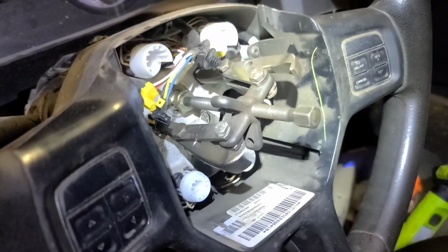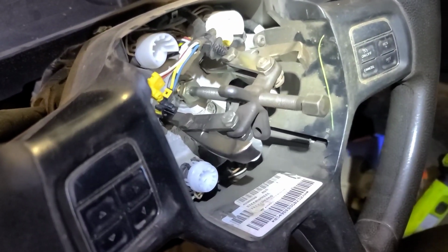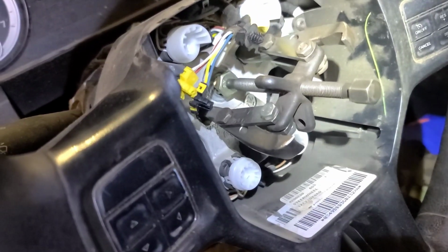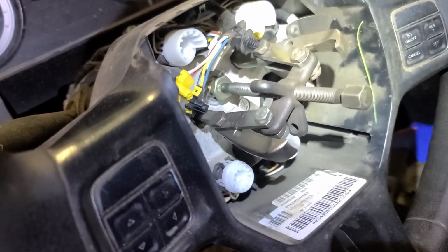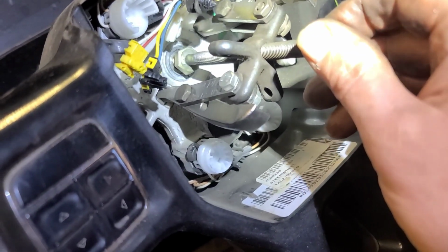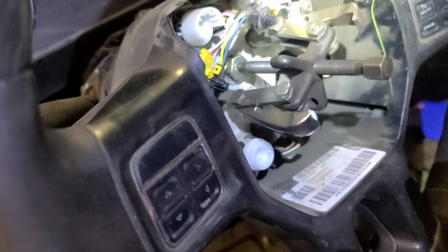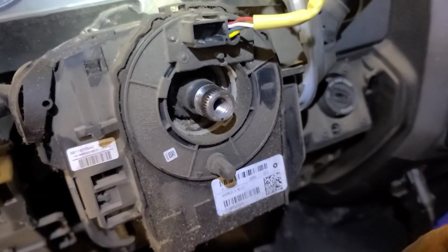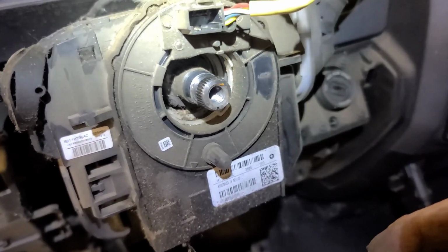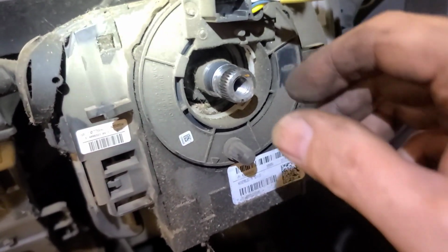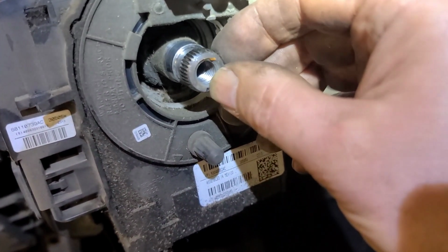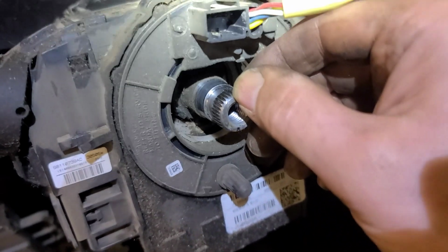So I modified the jaws on my little puller here, and I took a 8mm bolt and drilled a center hole in it. And I'm still having difficulty. This thing is not coming off. Well, when I was about to give up, it finally came. Tapping on the puller when there's pressure on it. And yet the splines, there's a master spline on here. I did mark it, but there's a master spline on here by the looks of it.